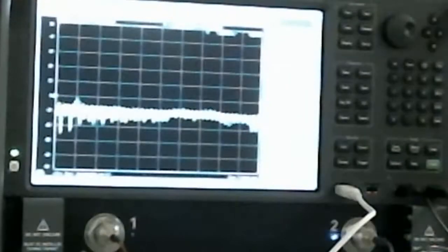Normally when you do a VNA measurement and say I want to measure at minus 10 dBm, that's minus 10 at the port. If you have, for example, a probe station, or you're going into an anechoic chamber, and you say I want minus 10 dBm at the antenna, it will give you calibrated power at the end of the cable, within the uncertainty of the power sensor.